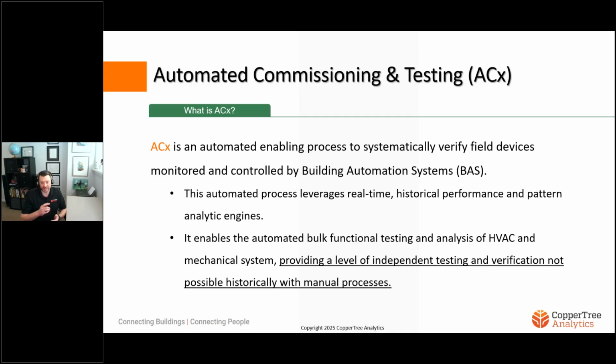We are exercising the systems in a way that is more thorough than would be done by your typical process in the commissioning phase, which is the contractor tests their own work, gives a report to the general contractor or the commissioning team, and says everything's been tested. Yet when you get to the commissioning phase, the functional test and the commissioning is a sample, maybe 10 or 20% of the total number of systems that have been implemented within the building. It leaves a lot of room for error with regards to deficiencies.